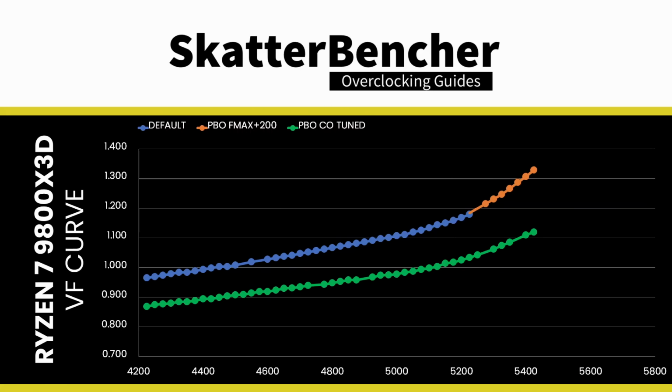Here you can see two VF curves of the Ryzen 7 9800X3D, the default curve and the one from OC strategy number 2 with the -40 Curve Optimizer. We can see the law of diminishing marginal returns. The higher the frequency, the less additional frequency with every step of additional voltage. For example, on the default curve, increasing the voltage from 1 volt to 1.05 volt gives an extra 300 MHz, but increasing from 1.1 volt to 1.15 volt only gives an extra 175 MHz.